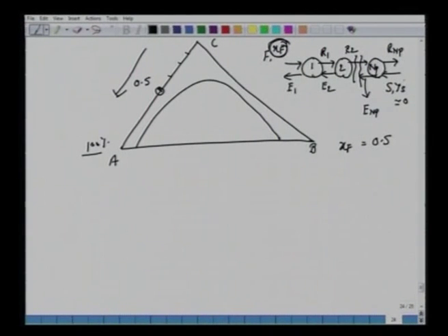We know the solvent is YS of 0. So this is 100% pure solvent. So there is no solute in this. So this is point S here. We can connect this point. All right. So if we know the amount of F, we know the amount of solvent, we know these compositions. Essentially, mathematically what we are writing here is F plus S. We are writing this, giving rise to some mixture M.